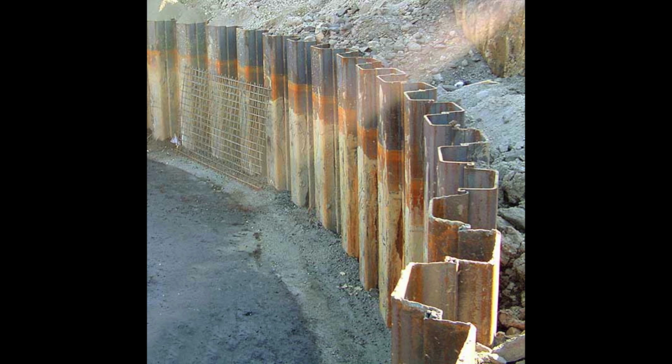The intergranular connection is lost, and the particles begin sliding over one another. An immediate drop in strength will occur. This image displays a sheet pile wall, retaining soil horizontally. A direct shear test needs to be run on backfill material before constructing such a wall, so that a safe design and construction plan can be implemented.